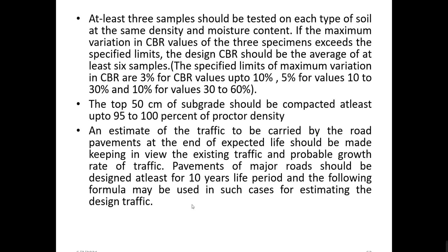So it is a routine practice to take not only the existing traffic. Along with this existing traffic, we should also take the anticipated traffic, or the probable growth of the increased rate of traffic that could come in the future, into view. And the design of a pavement should be such that the design life of the pavement carries the traffic up to a design period of at least 10 years. Okay, you have to take that into consideration.